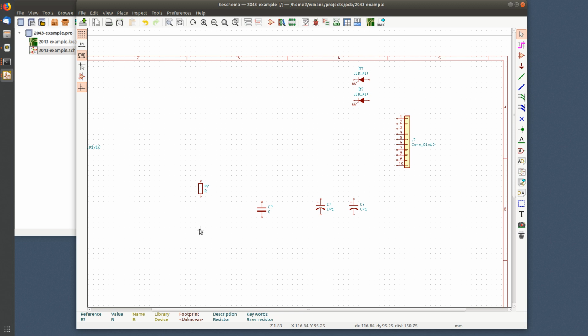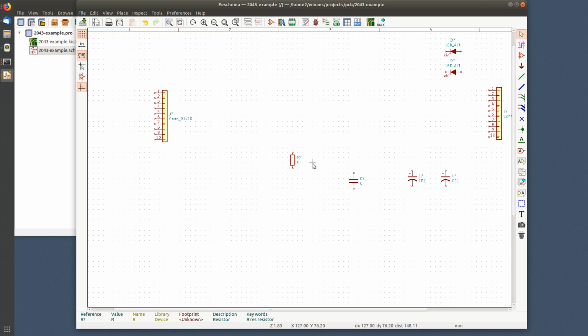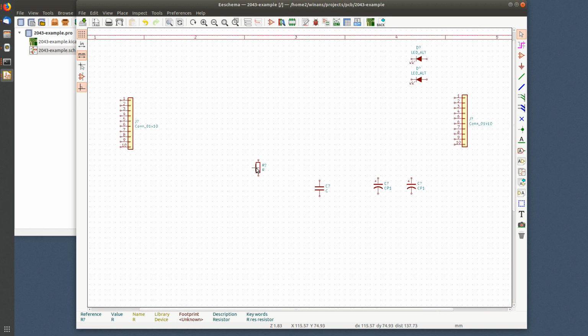Okay. Let's say you don't really want this resistor vertically, you want it horizontally. If you hover over it and hit R, it will rotate. Okay, so I can rotate it, hit M to grab onto it and move it. Maybe I want to put a couple of resistors over here, C. Now, if you're going to put a lot of them next to each other, you need to leave room for the description of the part. So maybe I'll copy it again, and maybe I need to put a third one up here. You'll notice we start running out of space.